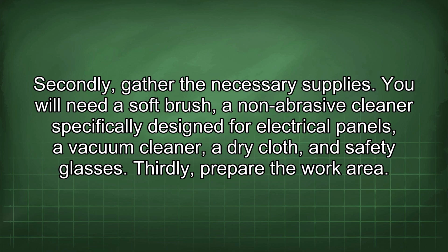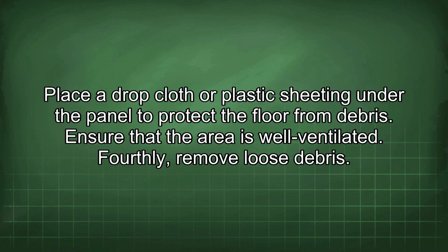Secondly, gather the necessary supplies. You will need a soft brush, a non-abrasive cleaner specifically designed for electrical panels, a vacuum cleaner, a dry cloth, and safety glasses. Thirdly, prepare the work area. Place a drop cloth or plastic sheeting under the panel to protect the floor from debris. Ensure that the area is well ventilated.